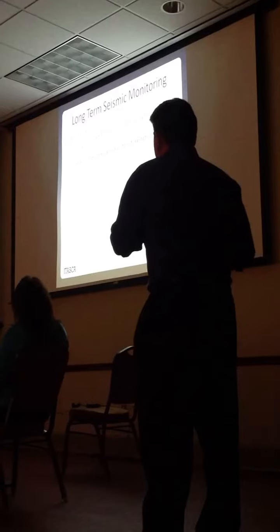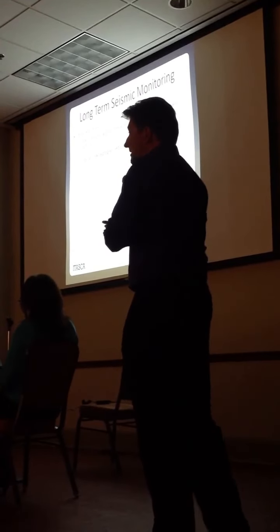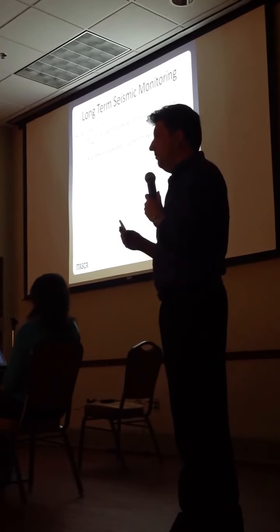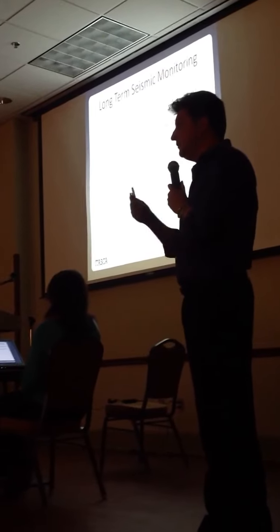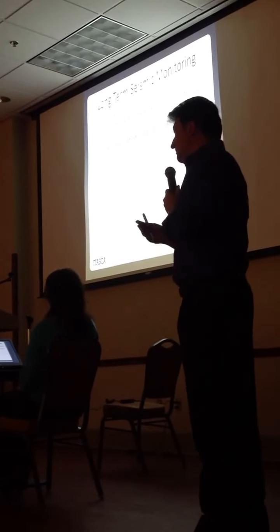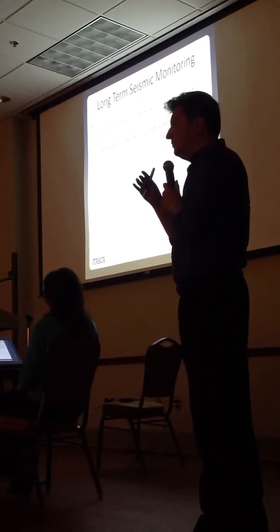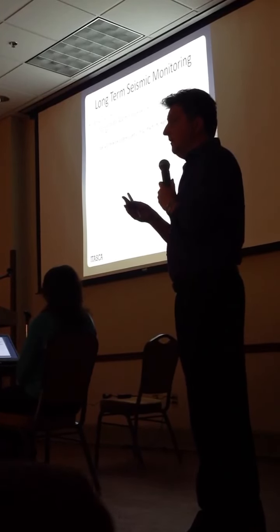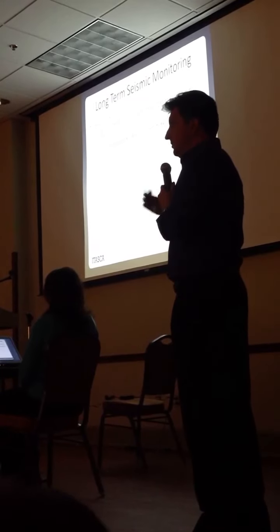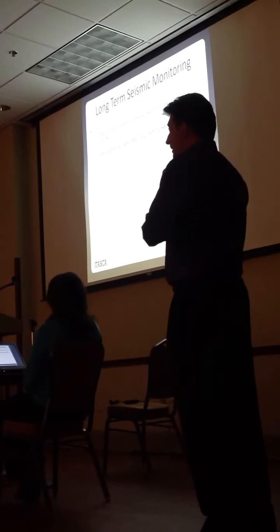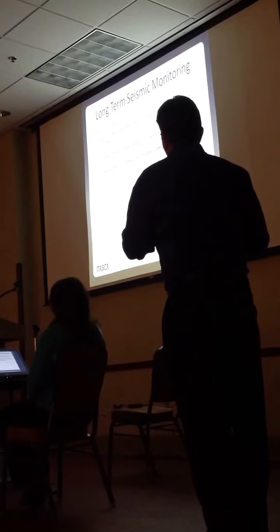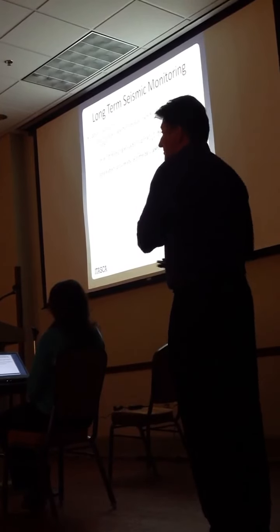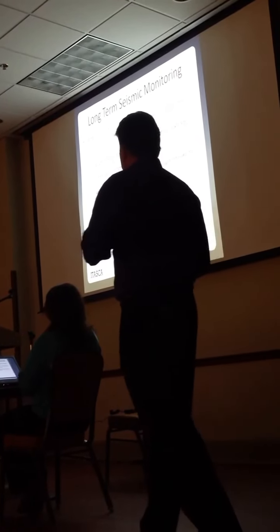We can observe any progressive build-up of activity that leads to a sinkhole burp, and we're now doing this in real time. You would have seen in the newspapers that we're processing the data and we raise alert levels so that people don't go on the sinkhole. We're currently at a level 2, which means people don't go on the sinkhole. So we're able to provide this advice on a daily safety level for any of the workers nearby.